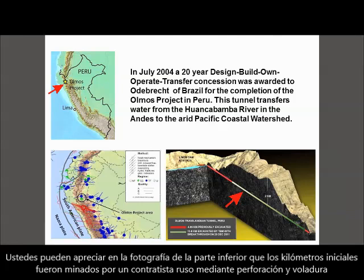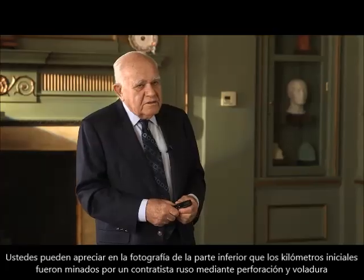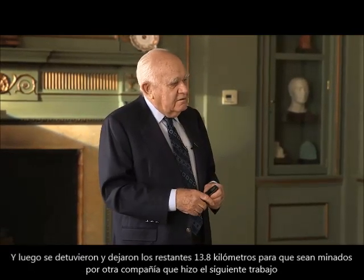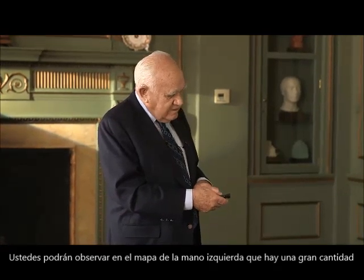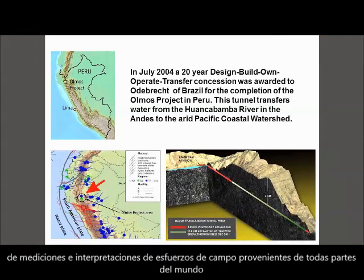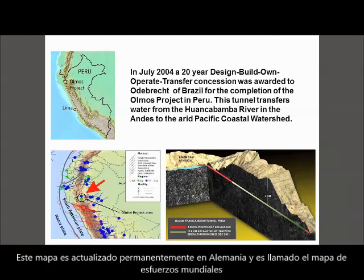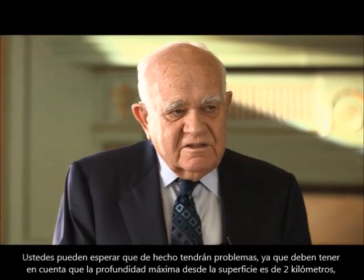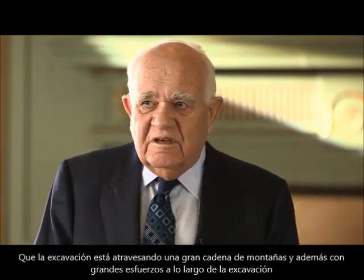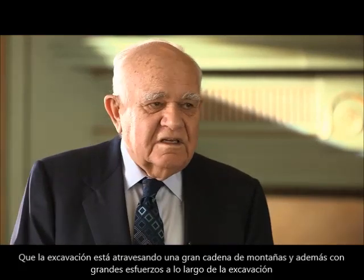The original, you see that in this illustration down here, the original few kilometers were mined under a Russian contract by drill and blast, and then that ended, and 13.8 kilometers were left to be mined by the company that did this. You'll notice also this map on the left-hand side here, which is an accumulation of measurements and interpretations of in situ stresses around the world, that is maintained in Germany, called the World Stress Map. And the tunnel is being driven right across the Andes, parallel to the highest principal stress. So you can expect, from the fact that it's 2 kilometers below surface at its maximum and is being driven across a major mountain chain with huge stresses across it, that there will be problems.